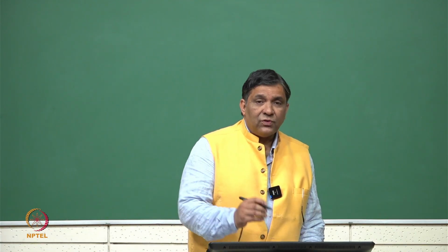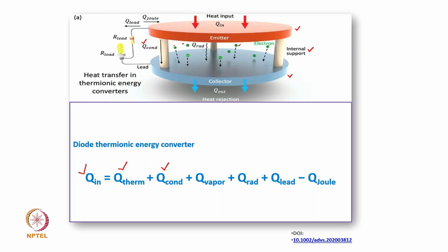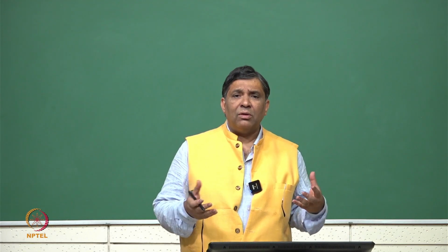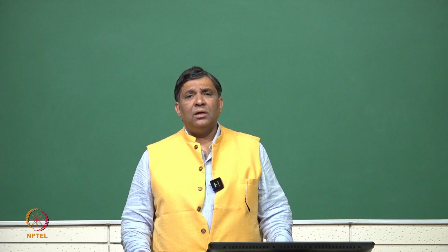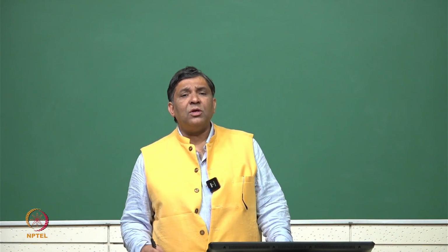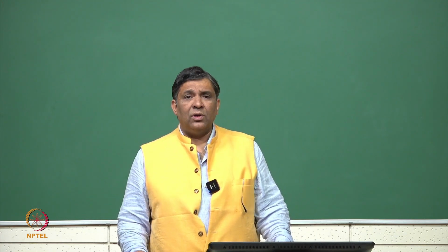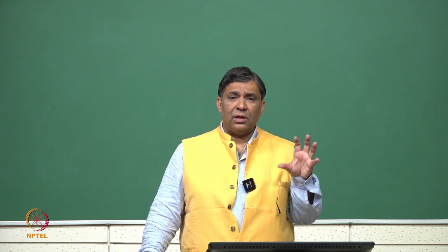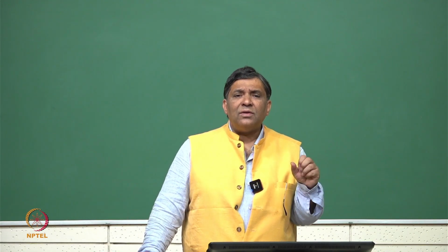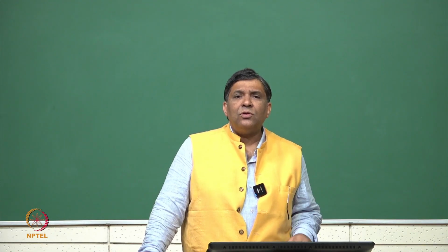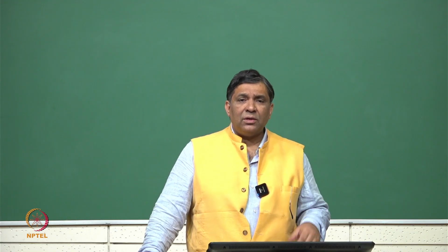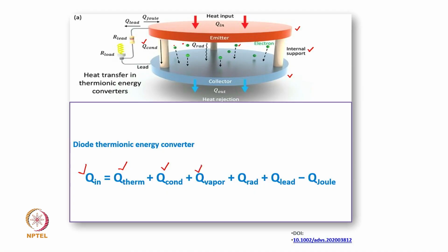In between these two electrodes, it has been purposefully added to this chamber, so that they become a sort of positive ion, and eventually they attract electrons, neutralizing those space charge electrons. But if we put this cesium vapor inside this thermionic generator, then there is another path of heat, that is through the vapor. So, we have another path, that is called Q vapor.